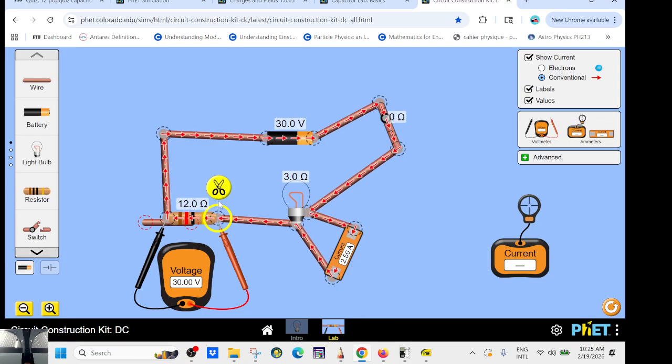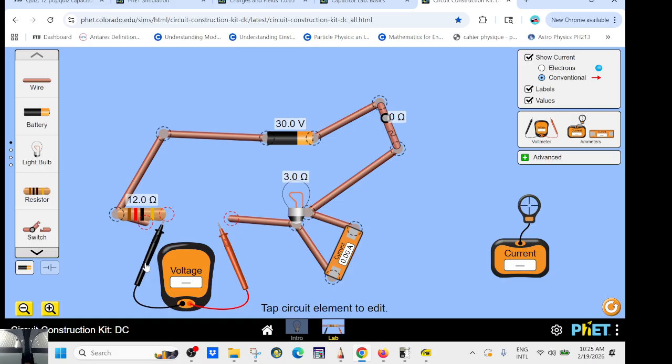So if I open the circuit here and place that in series, is there anything flowing now? No, because this one has such a large resistance that no current can flow. If there is no current through that resistance, there is no voltage drop, because it's R times I. So this is like a dead connecting wire, and this is a dead connecting wire.